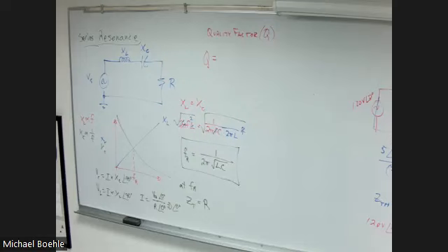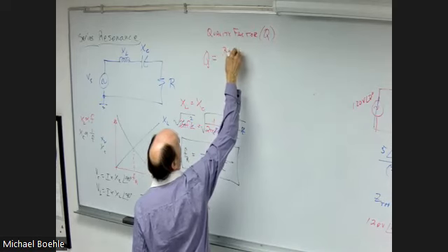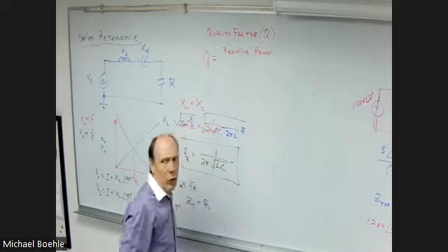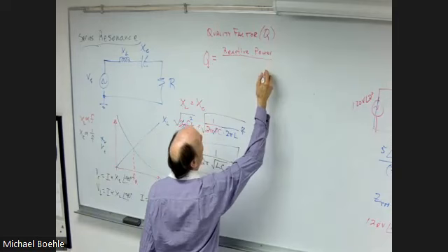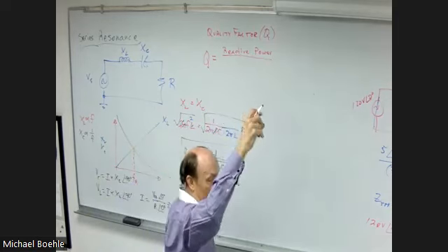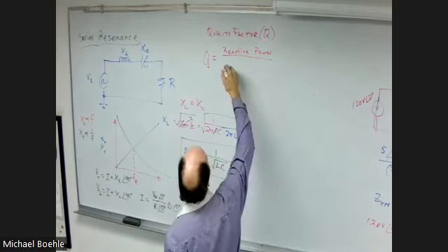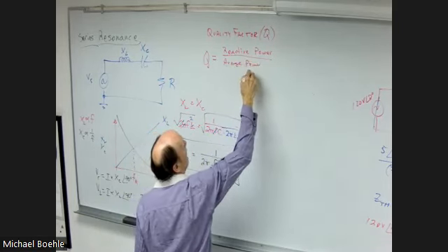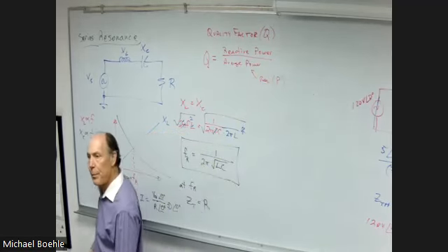So the Q of a circuit is a ratio of the reactive power, of course, we've been calling Q all along, just to make things worse, divided by the real power, average power. What I mean is real power, or what we've been calling P.